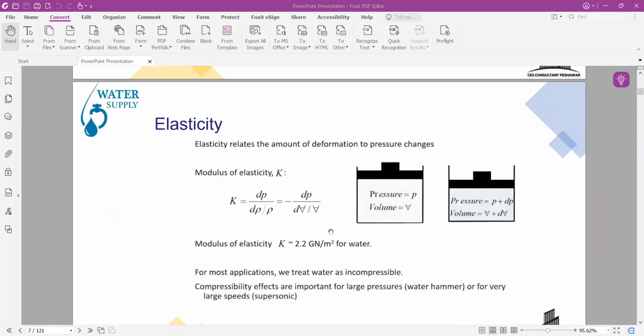Elasticity is a very important parameter in order to design any type of pipe, because the elasticity varies from material to material. So if you want to design a water supply system, then you should know about the material and its elasticity, mostly in the case of the hammering phenomena, where the transient occurs. So the material most affects the whole hammering process.